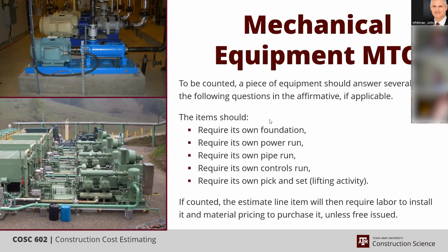And then from that, if you have that ratio, you can go, well, we know for every ton of steel, it's 35 hours a ton, and it's $3,750 per ton, and so on and so forth. And the metrics are really good for factoring if you have nothing, and they're really good for checking your detailed estimates when you do have a lot of things.